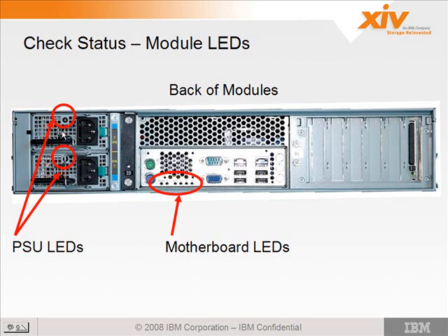And if it turns yellow, it indicates that that power supply has failed. There are also some motherboard indicators on the back of the unit, and we'll take a look at what some of those mean. Most of these are post codes, power on self-test, and the sequence in which they flash would give you an idea of what's going on.